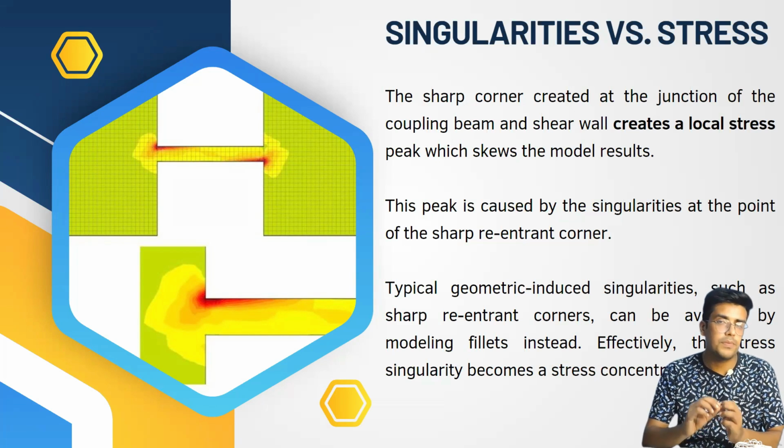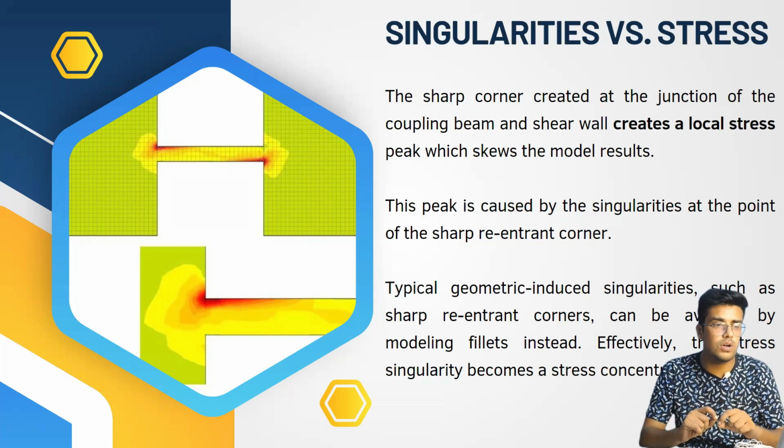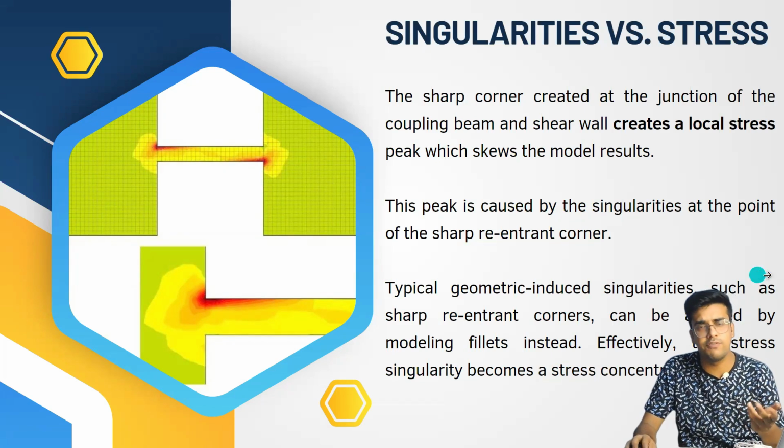Okay, in any case, you are not going to fully avoid the stress concentration there, but you can effectively convert that singularity into a bit of stress concentration. The singularity can be avoided by providing fillets and so on.